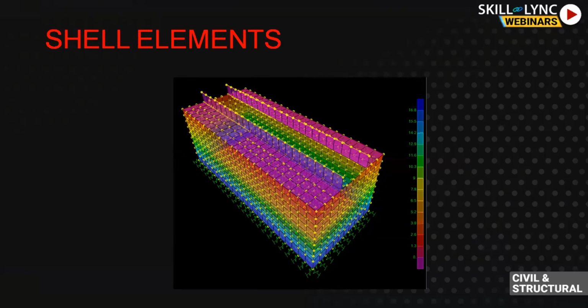Now, I would like to tell you, when it comes to structural engineering, this is a fuel tank I did. This is about a 5 meter deep fuel tank. You can see openings in the tank, but why I want to tell you how to model the behavior of a tank is a good question. When it comes to structural engineering, you can model them in finite element software like a shell structure, a membrane structure, or a plate structure. Briefly, I would like to explain why I chose shell elements.